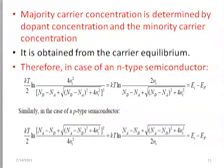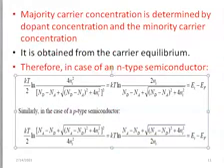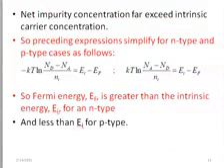If you assume Na minus Nd is much bigger than Ni square, so you let this one be equal to 0, you will be left with square root of Na minus Nd all square. The square and the square root will cancel out, and you have Na plus another Nd plus another. You factorize 2 and cancel it with this one, and for this you have your expression simplified to this.